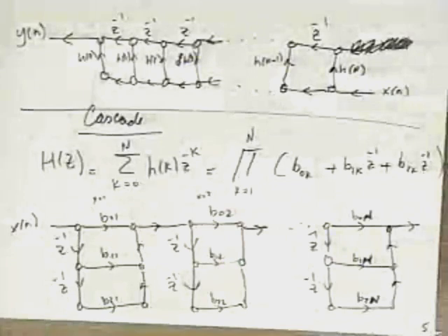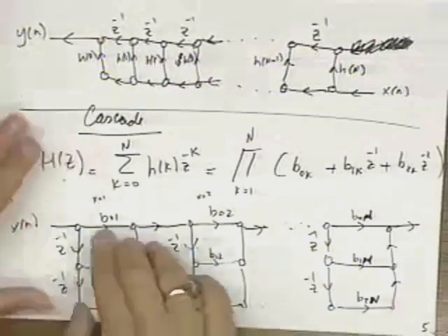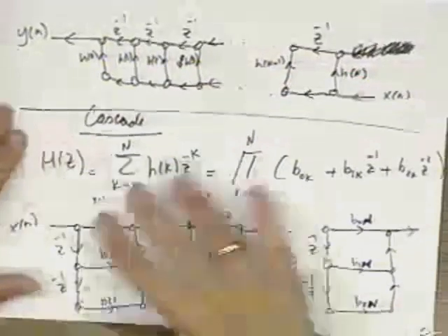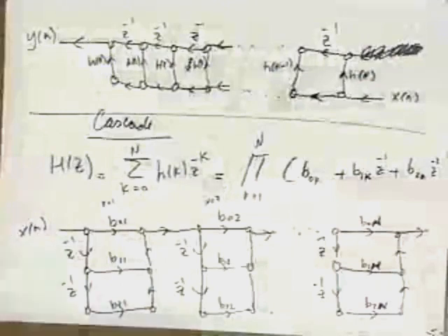And then if you multiply that 16-bit number by another 8-bit number, you get 24. You can't have registers that grow in length arbitrarily. You have to have some kind of truncation. It's called finite word length effects, or finite word length arithmetic, whatever you want to call it. And so that's called round-off errors, right? So besides the fact that the coefficients are quantized, when you do these additions, multiplications, and the numbers propagating from here to here, etc., there are round-off effects going on.